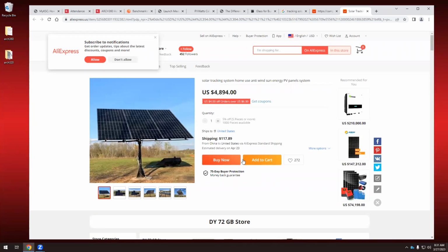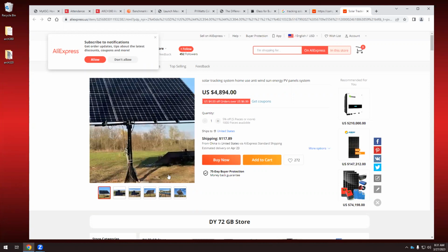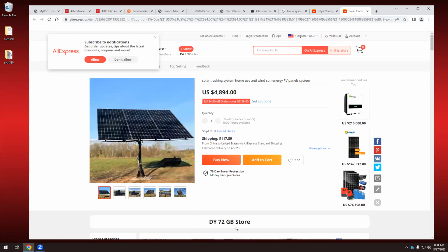If the sun rises in the east, goes to the south, and sets in the west, they adapt the azimuth angle and the tilt. When you have a solar farm, with PV arrays in the middle of nowhere, in the middle of a field, this is very efficient, because the more perpendicular the sun rays are to the PV array, the more the production.